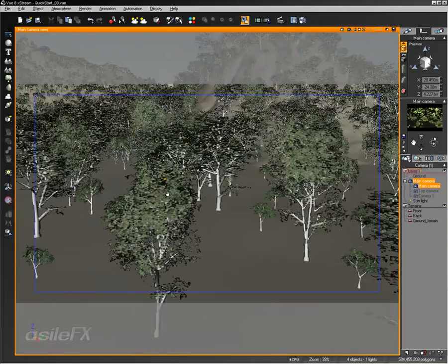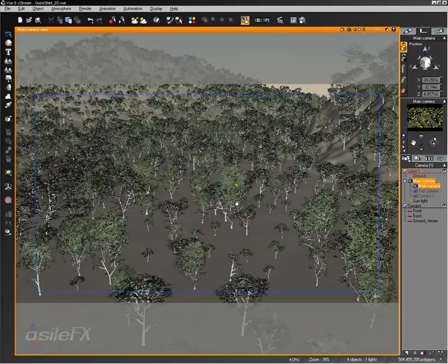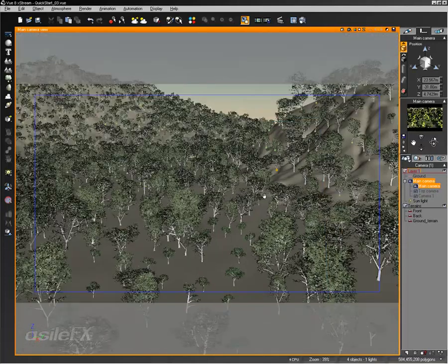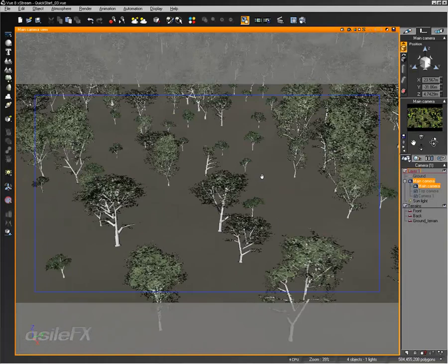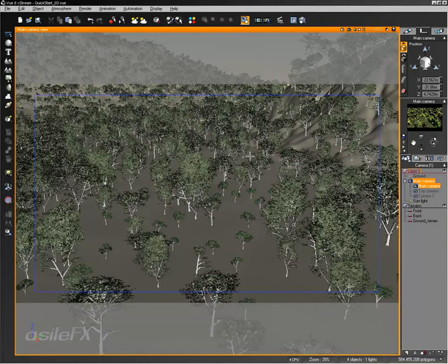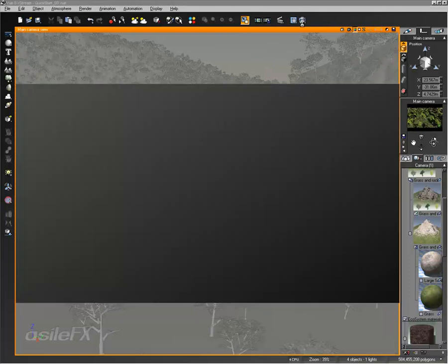What I want to show you is some of the preview options. And right now, as of View 8, a new previewing option is available, and it's called the shaded billboard. Now the actual geometry isn't showing up in the scene. What we're seeing is a flat image plane using normal mapping based on the lighting to show what this tree is going to look like. When we render, it's going to look much better than just this billboard and this flat shaded look.